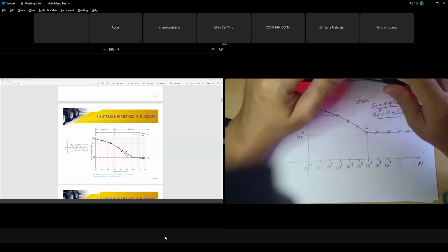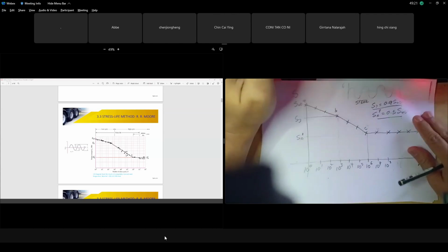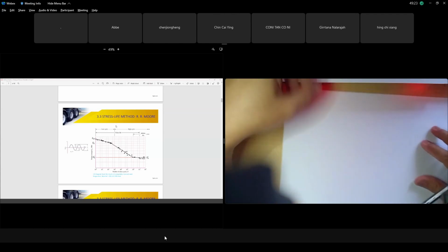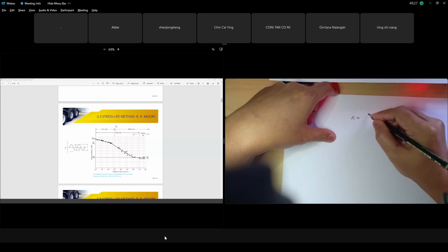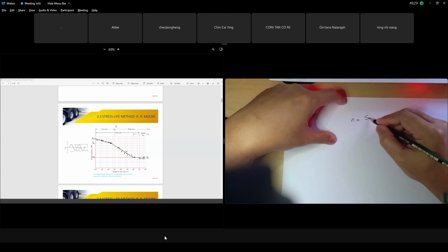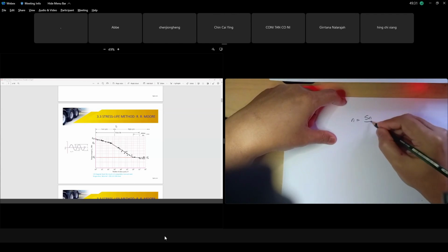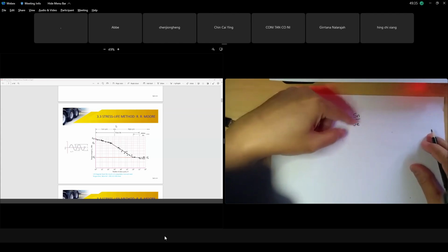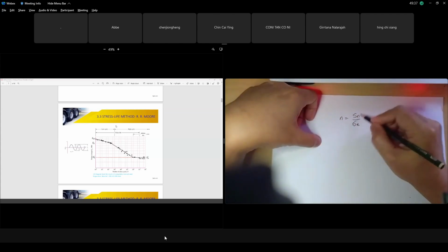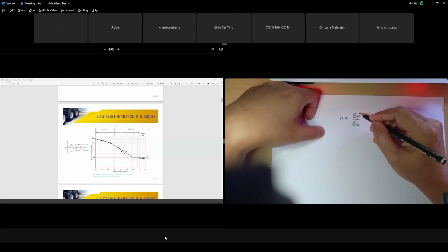Sometimes when we do analysis, as I said, this is a rough equation. For fatigue, the factor of safety is your endurance limit over your sigma equivalent. Sigma equivalent is always the denominator, and the numerator is the strength of your material. But for fatigue, I told you we cannot use SY, because we use the endurance limit SN. SN over sigma E.